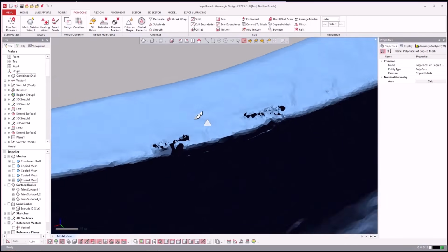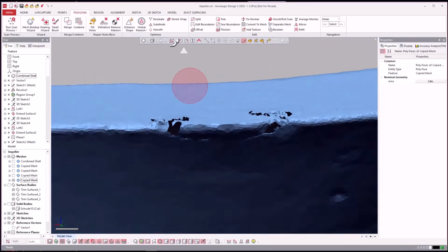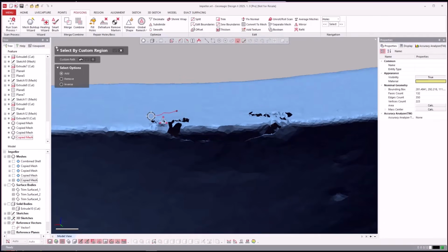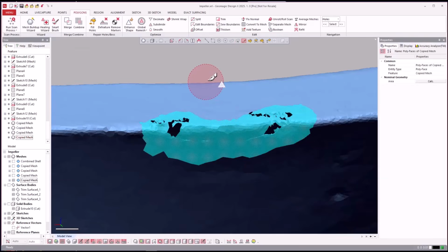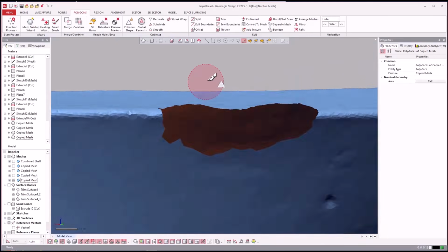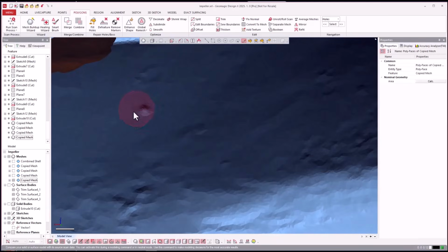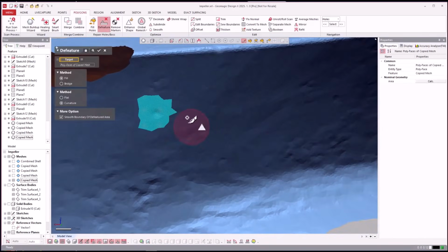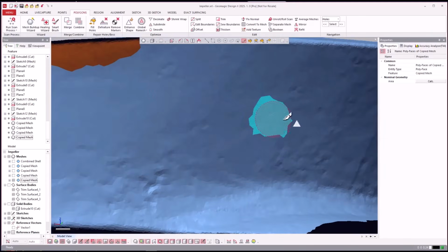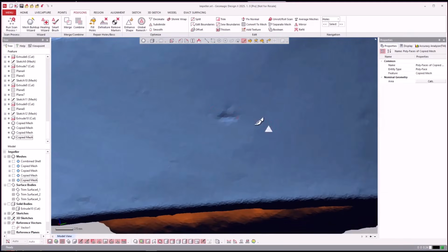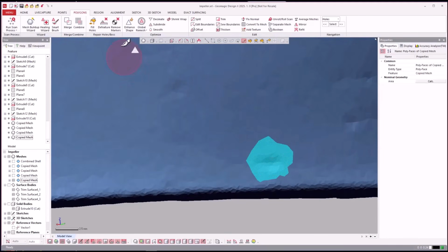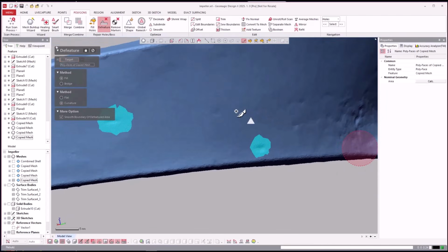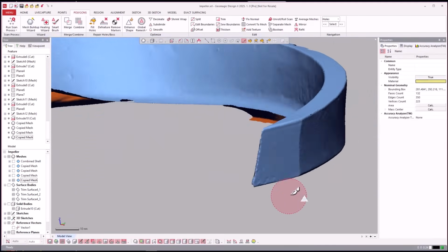And you got areas like this. This one, going back to that other tool, is probably the best way, right? You can come around here, hit accept, delete. You can do it that way. You could also use defeature, so I can click on that and hit defeature and have it just remove that area. And you can do these on multiple areas at once. So if I just grab this and that and then hit defeature, both of those are gone.